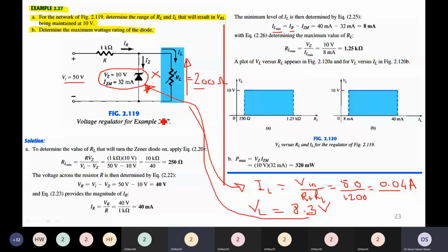No, look, power dissipation is the product of the voltage across the diode multiplied by the current through the diode. If we are working within the limits as provided by the manufacturer, then both diodes, Zener diode or the normal diode, can handle the current. But if we purposely make the current larger, more than the current the manufacturer has specified, then we will break down or rupture any diode, be it a normal diode or a Zener diode or any special diode.